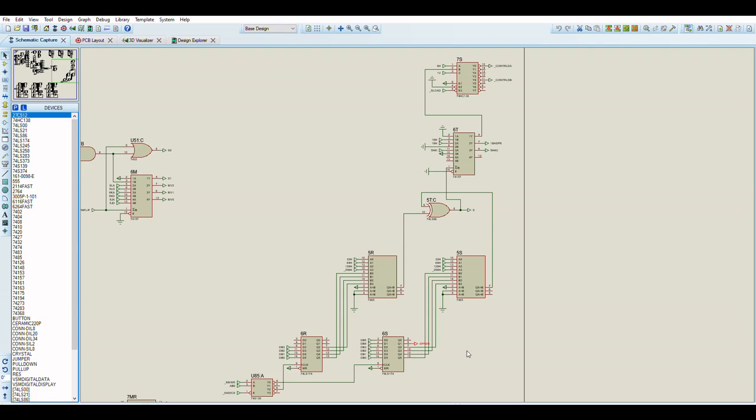I realized that if I wanted to make use of an effect called multiplexing, I needed a way of very simply switching off all of the Sprite update pixel logic until I was done doing writes to the Sprite register RAM during the screen time, and then enabling the sprites again after I've finished.